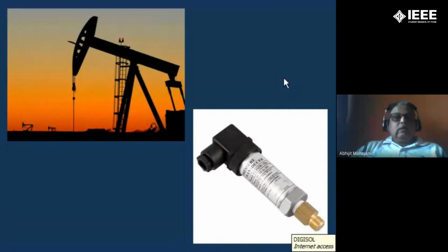Transducers are basically devices that convert one form of energy into another form. But transducers have evolved into sensors. Sensors are basically transducers which convert one form of energy into a calibrated electrical impulse as the output. These sensors will give you either 0 to 10 volts, or 0 to 5 volts, or 4 to 20 milliamps, or whatever. Then this becomes a sensor, otherwise it's just a transducer. So the sensors give you the data.